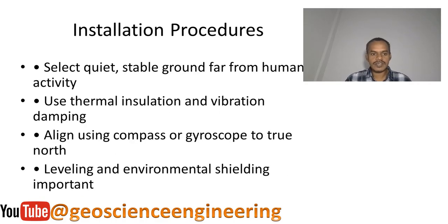And then we'll also discuss the installation procedures, the exact or best place to install this seismic station, far away from human activity, and also thermal insulation and vibration damping. We also discuss how to align this unit towards the north, and the leveling and environmental shielding, and also the way you are going to protect your equipment. Everything will be discussed here.